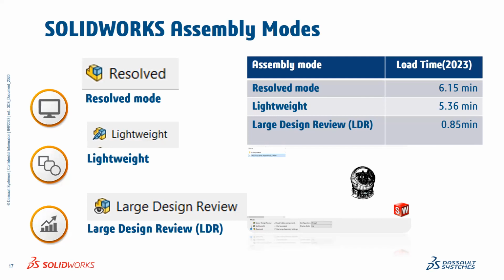If I quickly look, opening the assembly in resolved mode takes about 6.15 minutes. Maybe I do not need to open the assembly with resolved mode all the time. I will explain the resolved mode here, and then lightweight and LDR mode also.